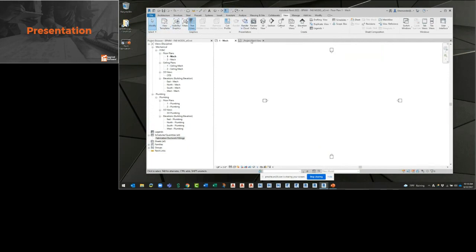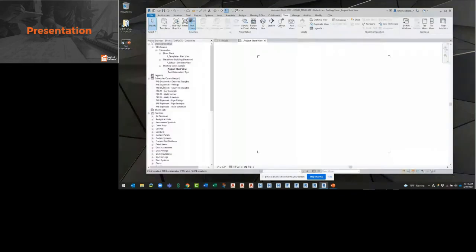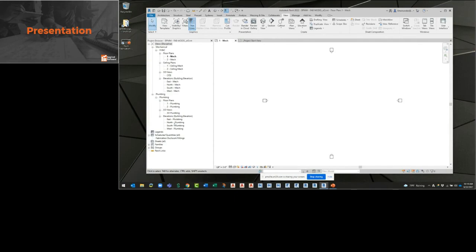Another thing that you can do with the template is this, and it's a faster way. I just learned this one through some friends of ours, coworkers who are developers for some of our internal tools. I didn't know this, but you can select all of your schedules in the template and right click and copy to the clipboard. There's no real command here, and if I go into my other project, there's no right click and paste schedules, so that would have thrown me off initially.